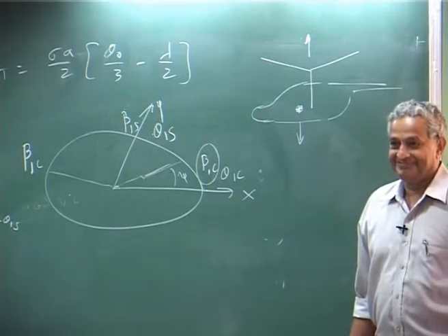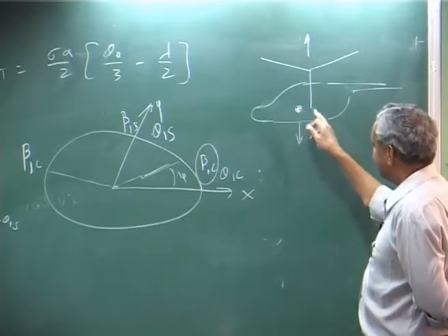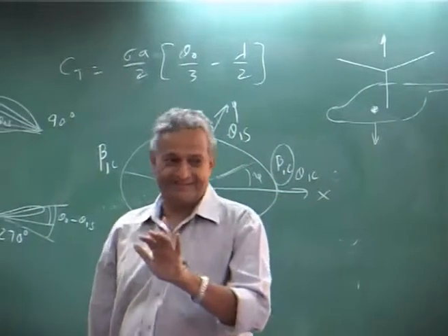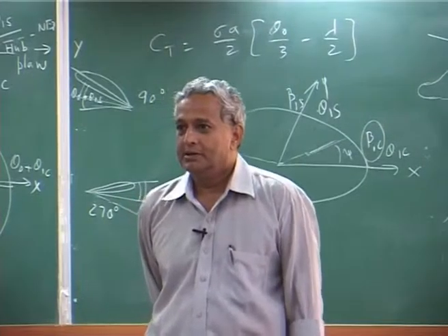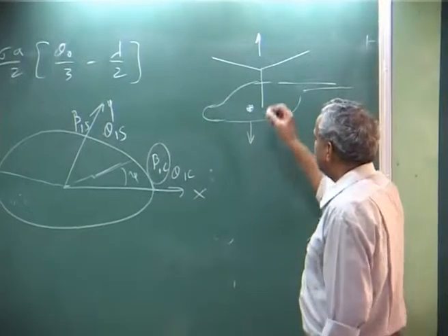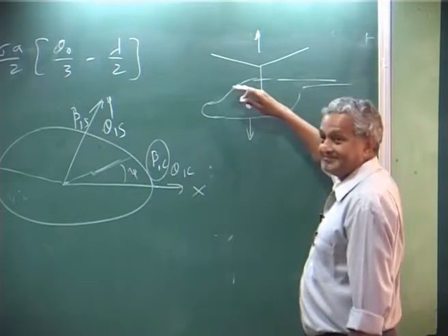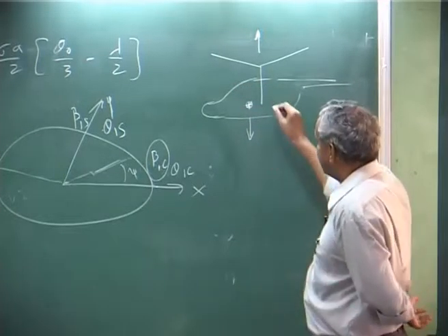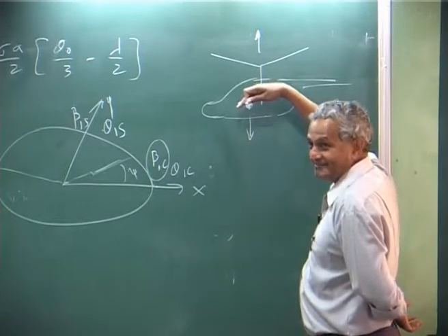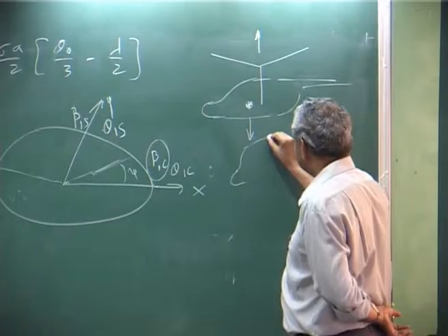So, you have to give, yes, cyclic, such that ultimately the resultant will come below, so that the helicopter attitude also will change slightly. Shifting in the sense, because this should be right below this, that is all. So, you orient this, suppose orient it means, because I want this point to be below. Suppose if I rotate it like this, what will happen? I am exaggerating the diagram.